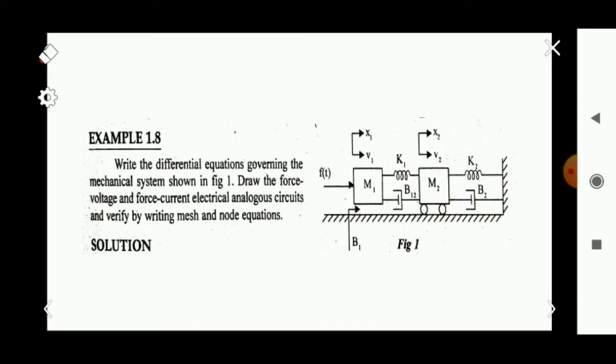So that's the problem, and this is the mechanical translational system. Okay, figure of a mechanical translation system. So we have to write the differential equations governing the system, and also we have to draw the force voltage and force current analogous circuit.